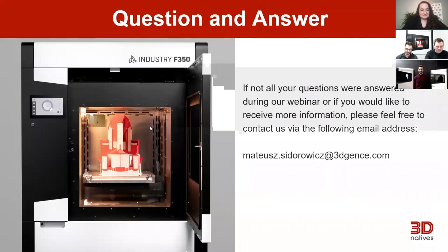It's a great question that has really been asked for years now, and it has driven the material market to try and deliver versions of the materials that are free, or at least display fewer problems due to the printer itself not having the features required. So let's take a desktop device without an enclosed chamber, no heated environment. Okay, some parameters are deal breakers. If your nozzle can't go high enough to actually process the material, you can't really do anything about that.